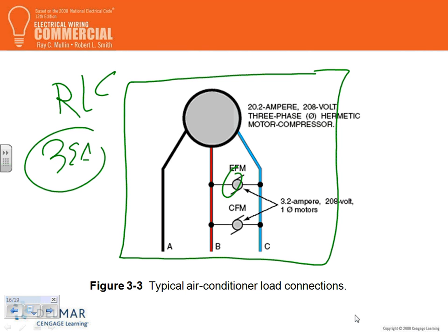You have a big box chiller with its own controller. Again, I'm looking at it as a construction designer. You have a big box with a controller. My job is to bring a feeder to this box, a disconnect and an overcurrent protection device. Now, if you're designing this box, getting into the guts of the box, that's a whole different story. If I want to design what's inside the box, then you get into is it single phase, is it 3 phase, and so so forth.